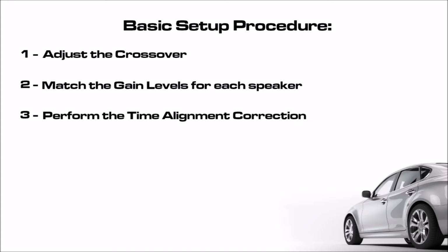It is extremely important to achieve a lifelike soundstage, avoid cancellation and phase problems. After these 3 steps were taken, we strongly suggest saving the settings to all memory preset slots available on Core1. The reason for that is, if you by accident push the memory button, there is no risk of loading an empty memory preset without the crossover settings, which is necessary for proper speaker operation and protection.